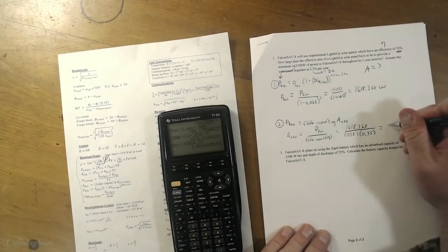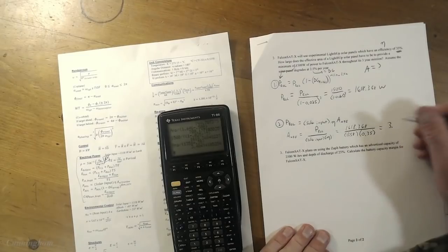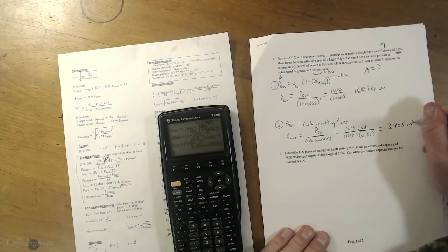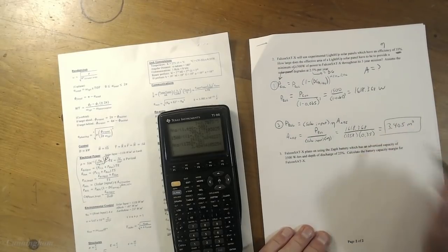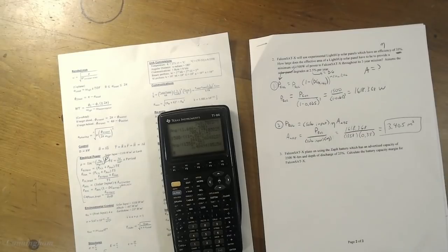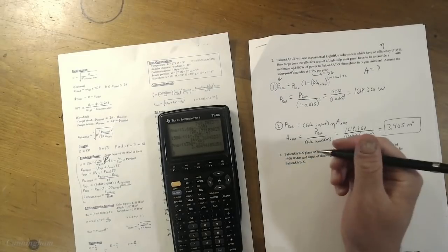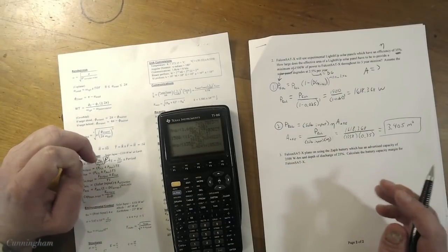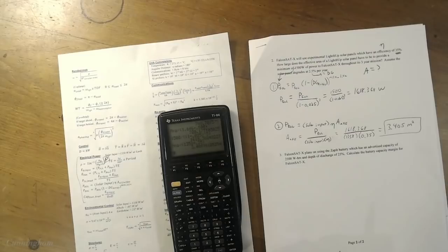Good. That means that no matter how we shape them, they can be a circle, they can be any old shape. They have to be at least 3.405 square meters to produce enough power at the beginning of the life of the satellite. Cool. Satellite solar panels take a lot of abuse, so we do have to plan for them to fall apart over time. Okay, let's see. Question 3 says FalconSat 10 plans on using the Zapit battery,